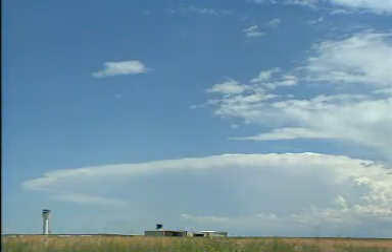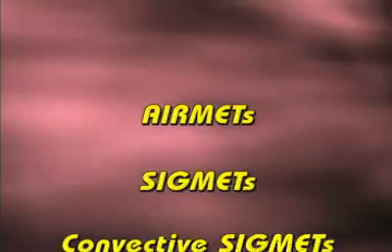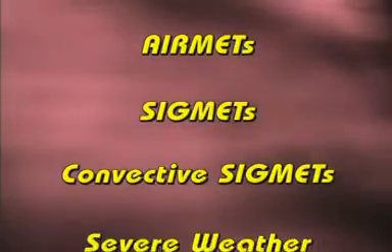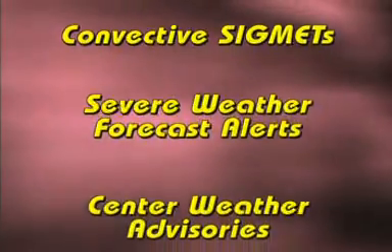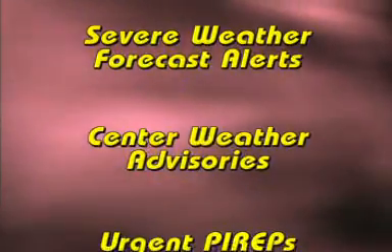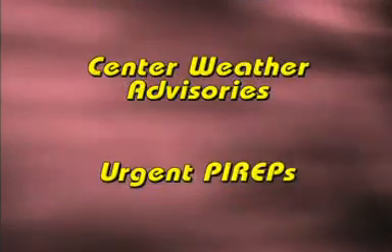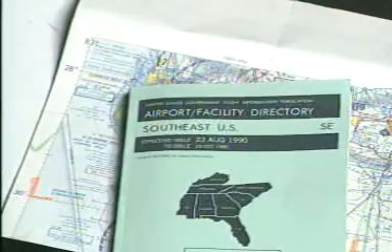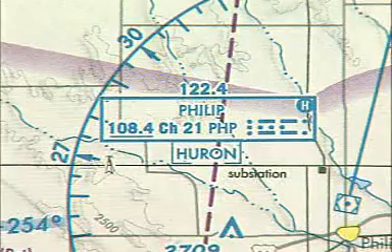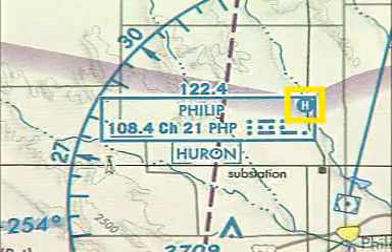Information available through this system includes AIRMETs, SIGMETs, convective SIGMETs, summarized severe weather forecast alerts, center weather advisories, and urgent PIREPs. The NAVAIDs and frequencies used for HIWAS can be found in the Airport Facility Directory. NAVAIDs with HIWAS capabilities are also noted on aeronautical charts.